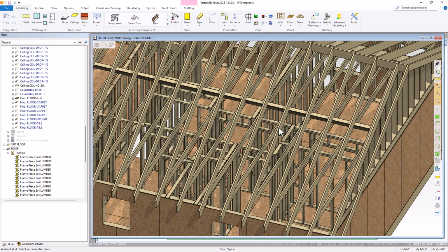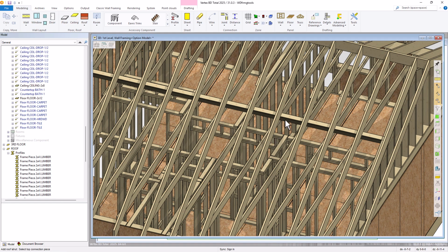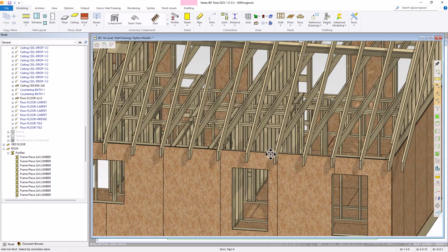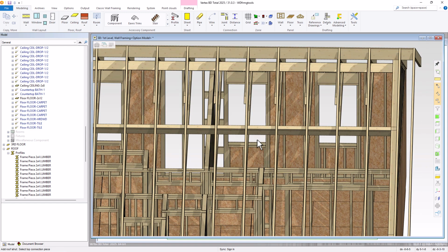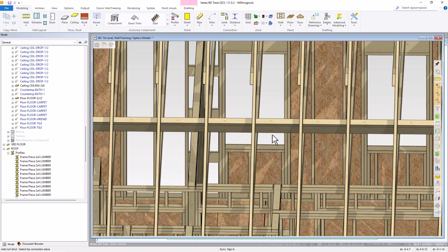To add struts to your 3D framing model, use the Zoom and Rotate tools to select the desired parts or members. You may need to hide certain objects to achieve an unobstructed view of the model. For example, I will add a strut to support the Strongback. For the first selection, select the 2x6 edge profile of the Strongback.